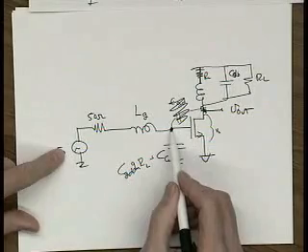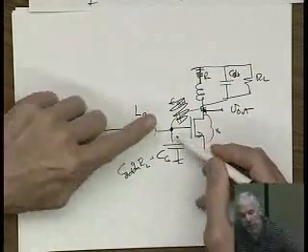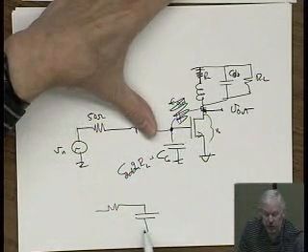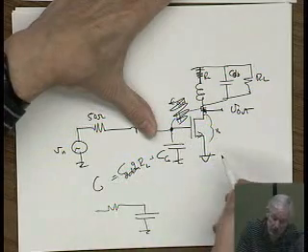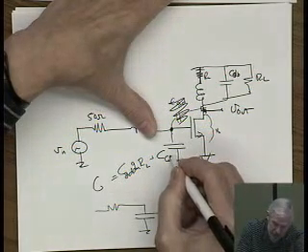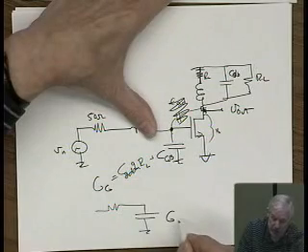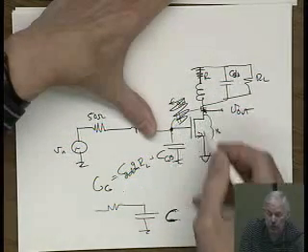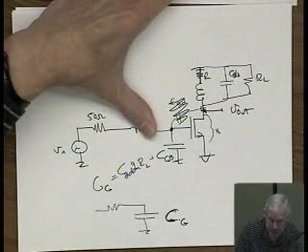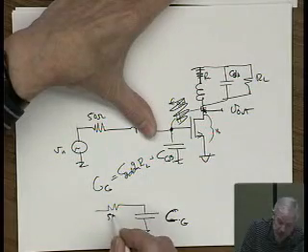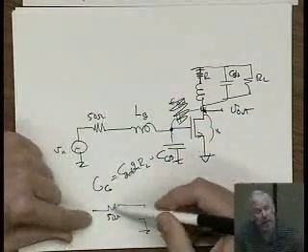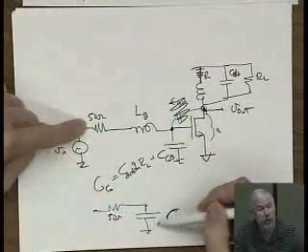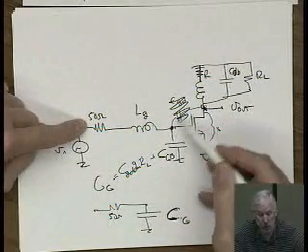Let's calculate the voltage on this point right here. Now, as we go up in frequency, the way we've been analyzing these circuits, let's call this CG, gate to bulk. Let's just call this C gate now, all the capacitance together, including the Miller multiplication of that. C gate, here's this 50 ohm thing, okay? So you'd say, well, geez, I have a time constant, a roll off on this input of 50 ohms with this C gate. All this capacitance on this node, including this Miller multiplied value.